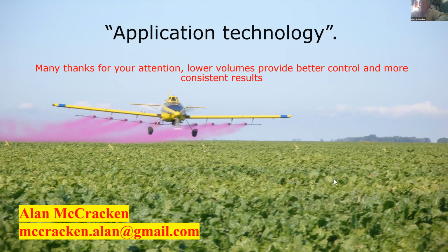As I said, practically all the product applied by air in South America is applied in what you would call very low volumes, 1 gallon or less, for the very simple reason, the operators have proven that we can control evaporation, and by controlling evaporation loss, we get better results. We get more product to the target.